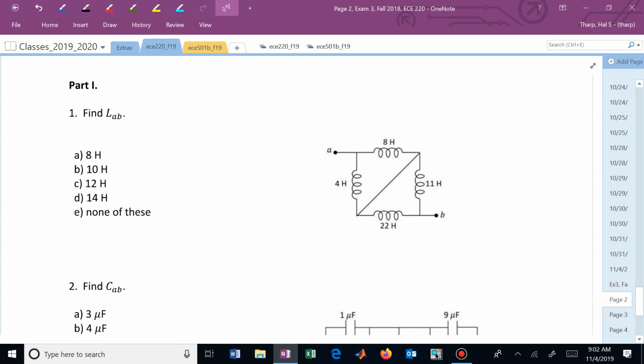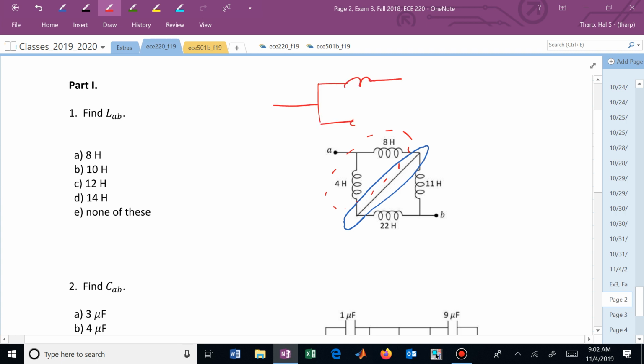Looking at this, obviously you need to remember how to combine inductors, but you want to start looking at maybe obvious simplifications. The one that you would see right away is that connection of those 2 points. Now you can put on your morphing goggles and see that these 2 are in parallel, as are the next 2. Now we're looking at the series combination of 2 parallel combinations.